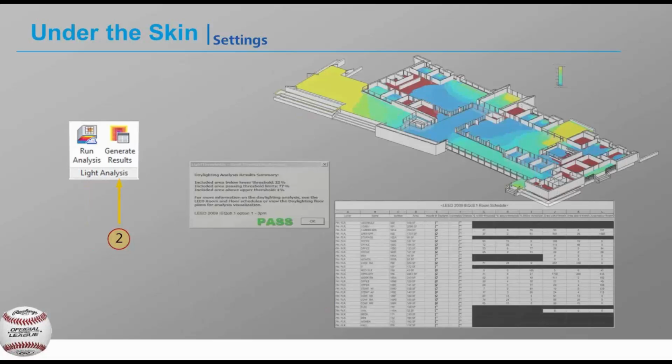So if you want to go into another tool like the Rendering Illuminance tool, or even into an advanced tool like Radiance, you can use these values to get similar results. The Illuminance thresholds are automatically set for the analysis type. In this case, LEED v4 requires a 300 to 3,000 lux threshold range. And down at the bottom are the cloud credits, how many are available on your account and how many are required for this type of analysis.